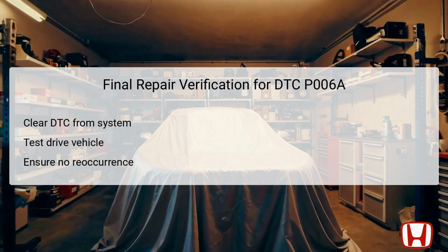After completing the troubleshooting steps and conducting any necessary repairs, it is crucial to verify the repair outcome. Start by clearing the stored DTC P006A from the vehicle system using the Honda Diagnostic System, HDS, to reset any fault indications. Following this, a test drive is essential to ensure that the vehicle operates normally under various conditions, replicating typical driving scenarios. This test drive helps ascertain whether the repairs have resolved the issue effectively.